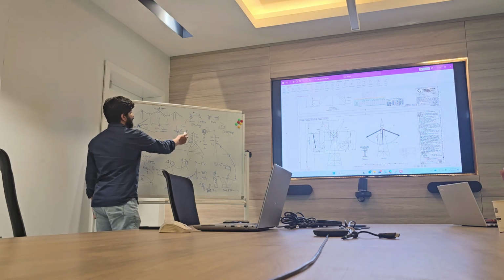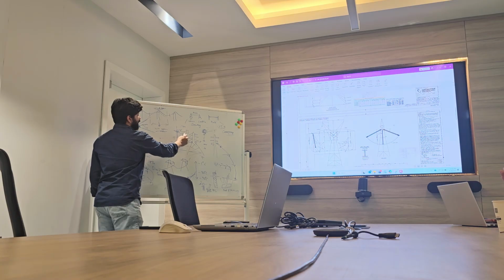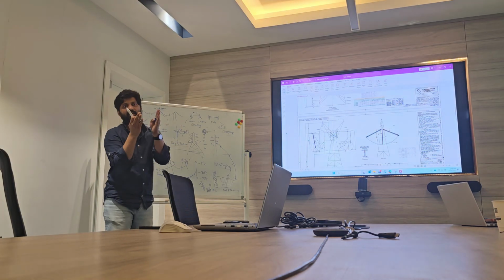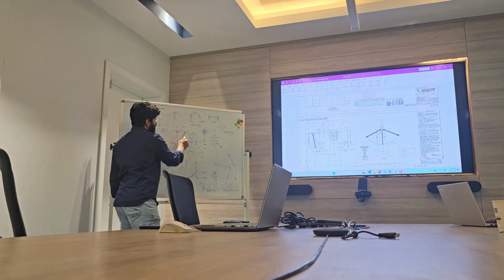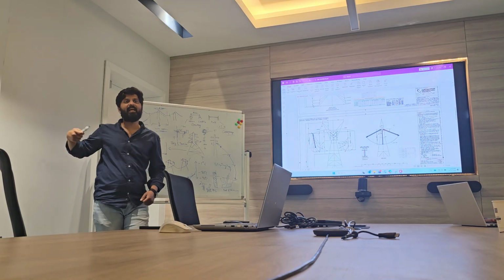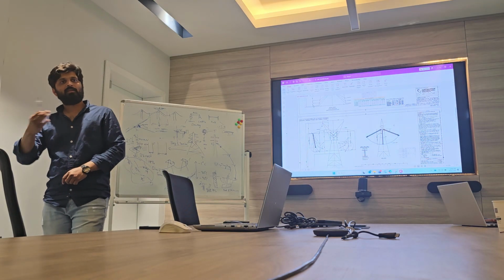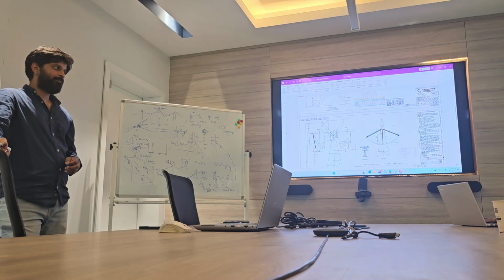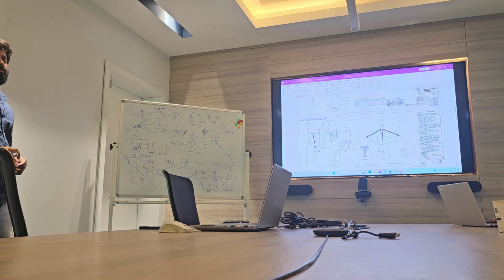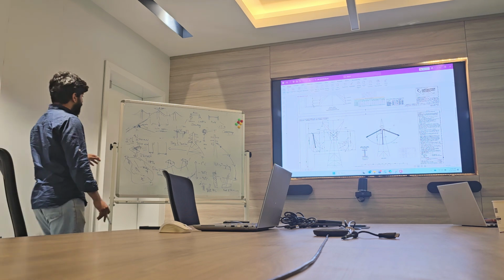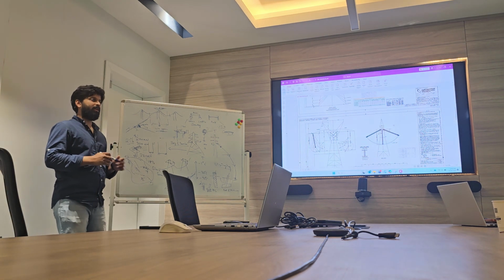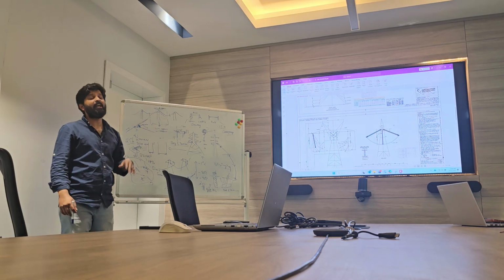in the area near a substation, where you come like this and you need your tower to be in front of the substation without any angle. Then your tower will be from one side angle only. It will not make line deviation divided by 2. This is called a terminal tower, the last tower before the gantry. In the middle of the line you can also use a dead-end tower, and you have to use it.